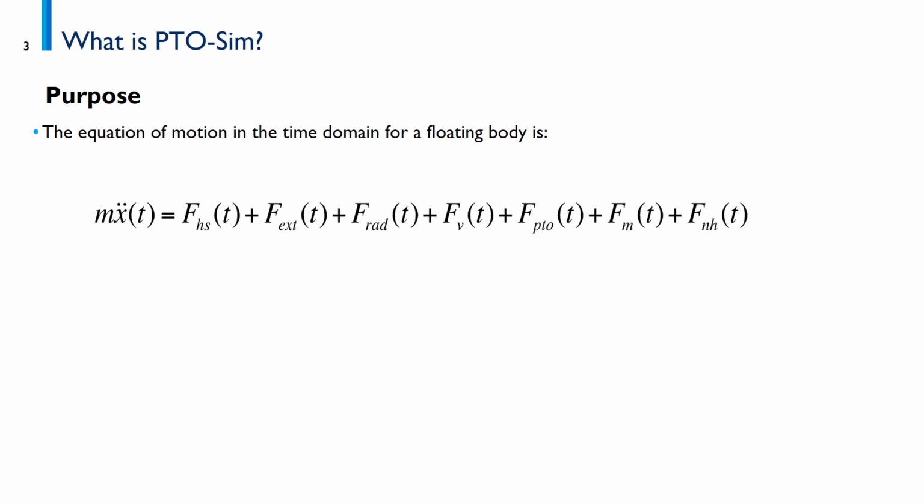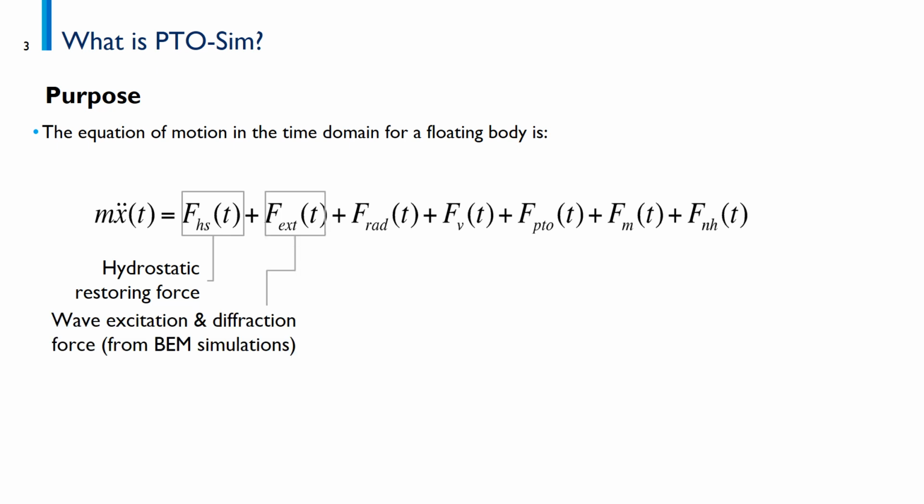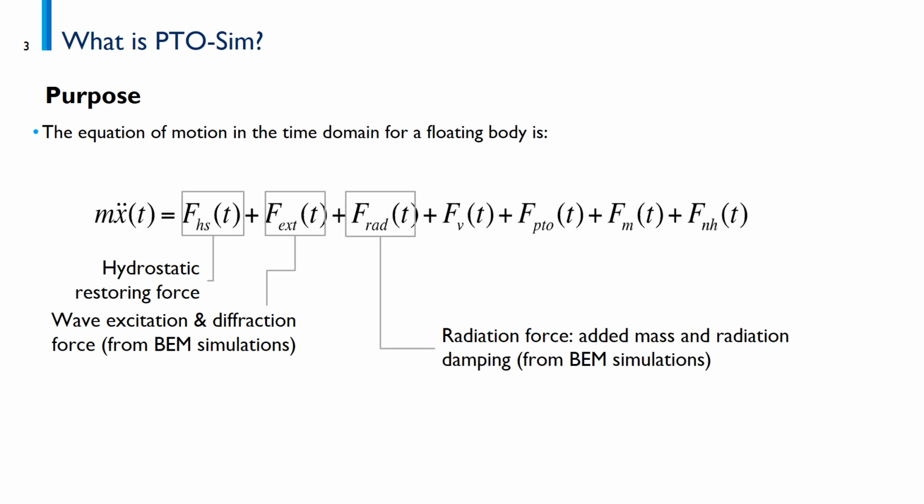This equation of motion has different terms such as the hydrostatic restoring force, the wave excitation and diffraction force. That force is calculated based on the boundary element method simulation results. We have also the radiation force, the added mass, and the radiation damping.